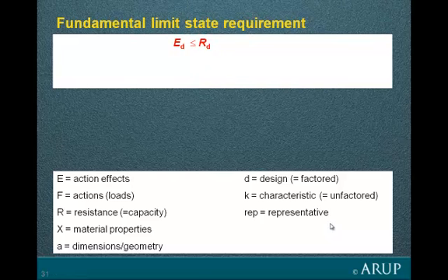The fundamental equation for ultimate limit states: we will always be asked to compare an E with an R, an action effect with a resistance. The second word that is used differently in Europe is the word action. An action is simply what in former British nomenclature we would have called a load. So loads are now actions, and an action effect is the effect of an action, the effect of a load in a structure.